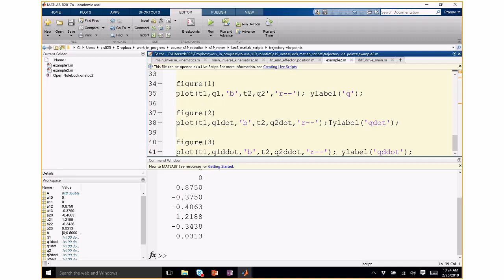Once you specify position for x and y, then for every point you do inverse kinematics, so you can get the joint angles. And so this really generalizes to Cartesian space. Cartesian space is when you want the end effector to move.